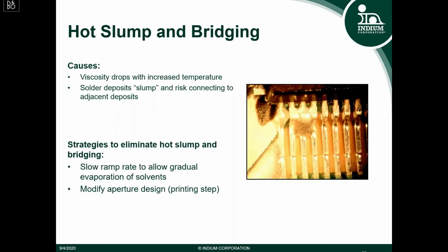Hot slump and bridging. Some of the causes of hot slump relate to the viscosity of the solder paste. As the viscosity drops during the reflow step with increased temperature, the paste could slump, and this could risk bridging two solder joints or more in the reflow step.